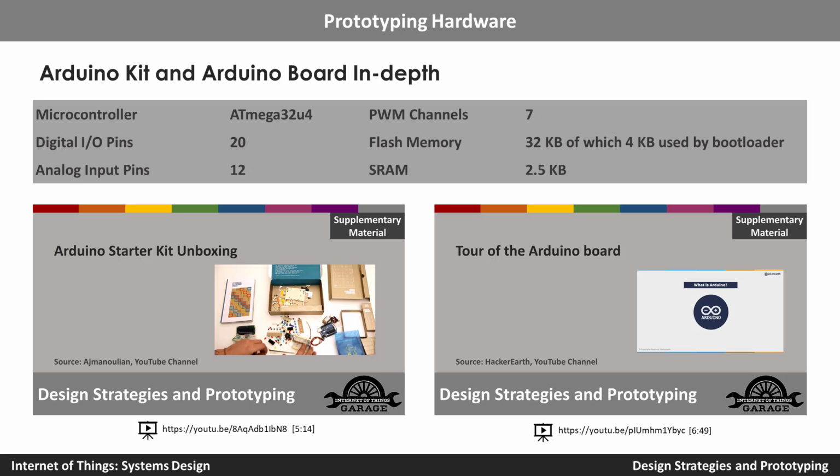But the traditional basic Arduino kit, where everybody starts learning Arduino, does not have that kind of clipping mechanism. You have to individually find out what the pins are, which are the digital pins and which are the analog pins. Then you need to combine different combinations and put in resistors to make sure the component doesn't get burned by putting more current through it. So you need to make sure what is the appropriate level of current expected by the particular component, and do everything by yourself. This is how traditional people do things, especially if you are doing an electronic engineering degree.